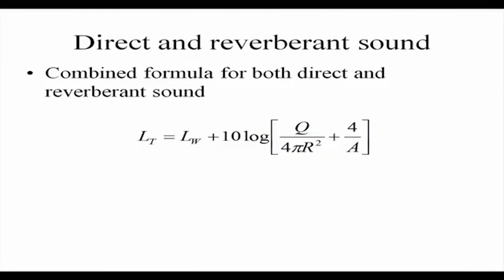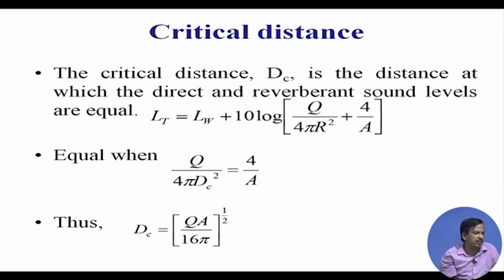So, if the machine is installed in a reverberation field and if I change the A, then the noise created by the machine will be reduced at this particular point, because the reverberation power level will be decreased. Only the direct sound will be there. So, this can be used as noise reduction. Okay. I have given one problem on that one, you can see that.